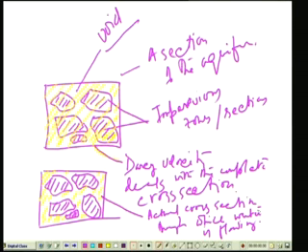So the Darcy velocity deals with the complete section, but the actual cross section through which the water is flowing is basically the voids. We are not including the impervious layers. As a result, this is known as the Darcy velocity.